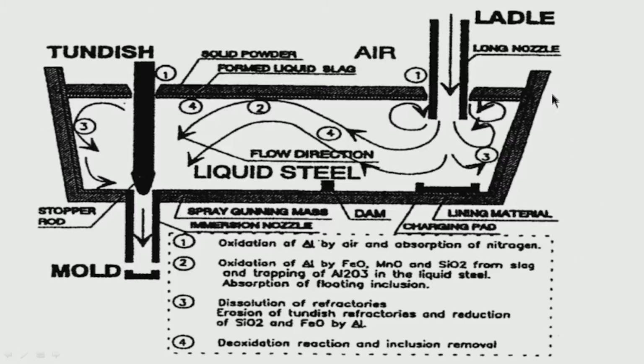Now, this is the total tundish. From the ladle, liquid steel is coming here. We do not want liquid steel to straight away go to the exit of the tundish. Why? We want liquid steel to remain for some time in the tundish. What we call the residence time. Residence time of liquid steel in the tundish should be high, so that whatever inclusions or exogenous entrapments try to ingress in liquid steel will get adequate time to float up.